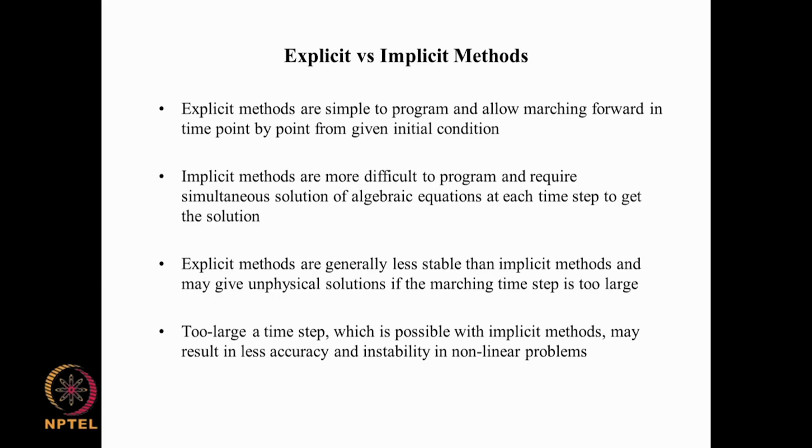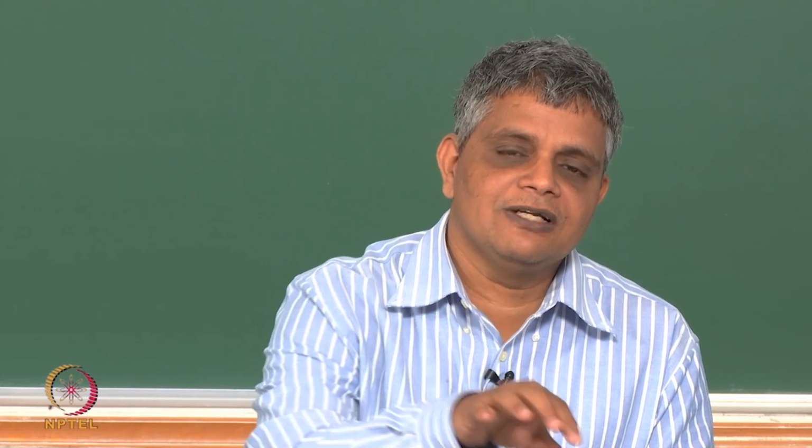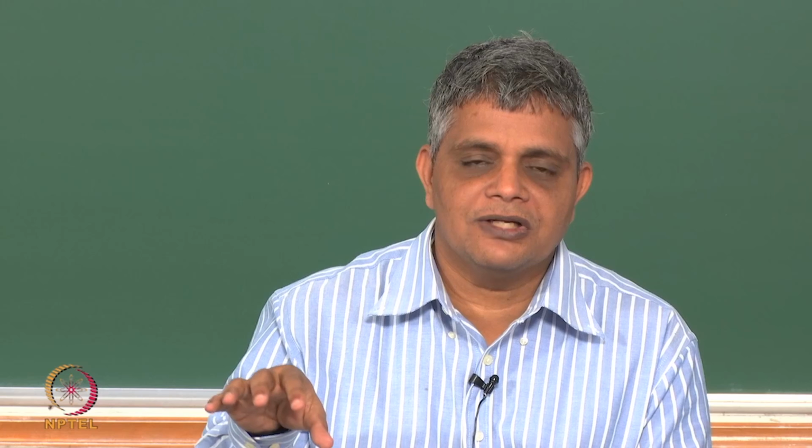So we can say at this stage we have looked at making finite difference approximations for time derivatives and space derivatives of any order of accuracy, and we have also seen how we can put all these derivatives together for a given equation, for example the Poisson equation or the unsteady heat conduction equation, and convert the governing partial differential equation into an algebraic equation at a grid point.